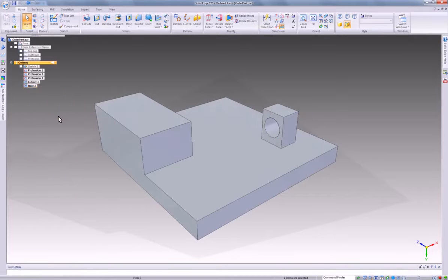Now this is the disadvantage of this. This is a very simplistic object here, which only contains 5 features, but when you get into a very complex structure, you don't know how the order dependency is between all the objects, and you have to either manually move your orders to combine or move to synchronous the minimum amount of features to make your modification, or you end up moving your entire structure all over to synchronous technology. So this is a limitation that it requires the user to determine what the relationships are and how many of those features it has to move to synchronous to make the modification.